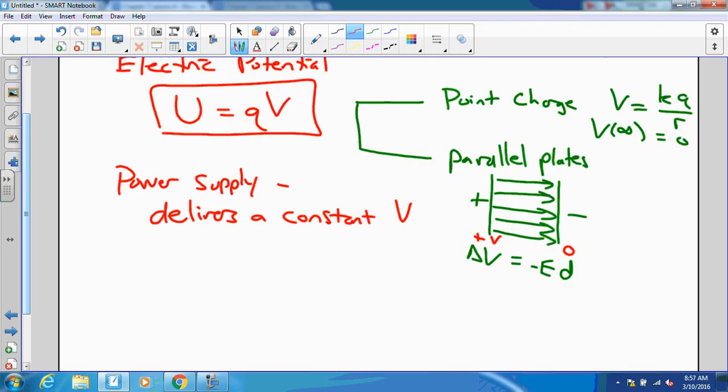All right. So what if we were to plot our results? To plot our results, what we would need to do is to get ourselves a nice grid. And on that grid, we would have to then mark different points of potential. Yes? Why is the voltage low on that line connected? Because this is hooked up to ground, trace it back to the power supply, this is at 0 volts directly.